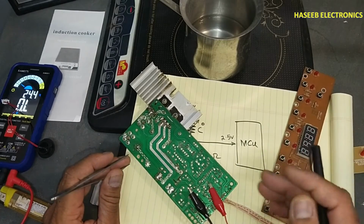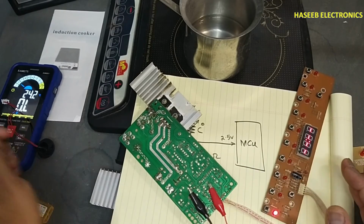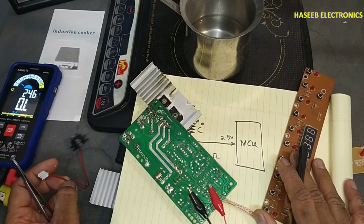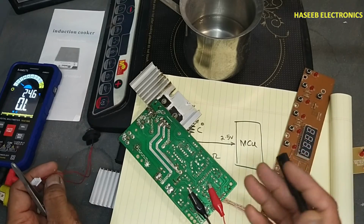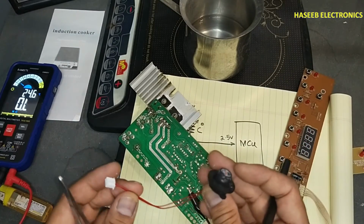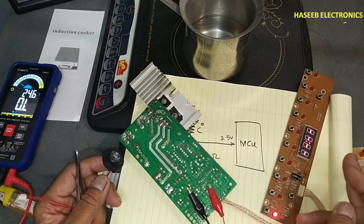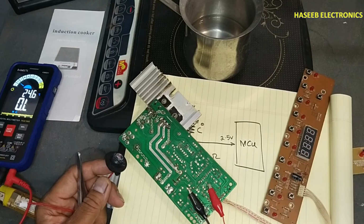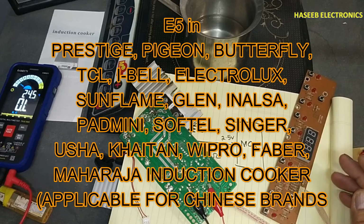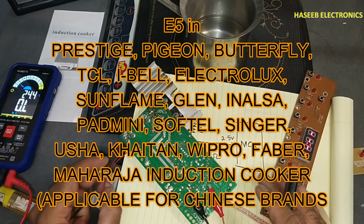And if while turning on, even after it has cooled down, it shows error, at that time we need to check this temperature sensor. In these Chinese brands, Mother Choice, Estrella, like that, these brands will show E3 error for this top surface sensor. The same sensor is used in Prestige to indicate E5 error. In these brands, E3; in Prestige, Pigeon, Butterfly, TCL, Usha, Singer, it will show E5 error.